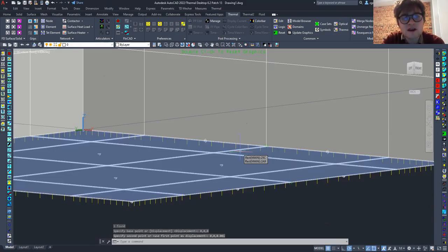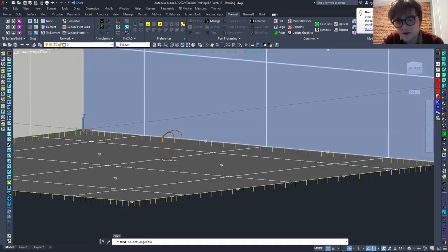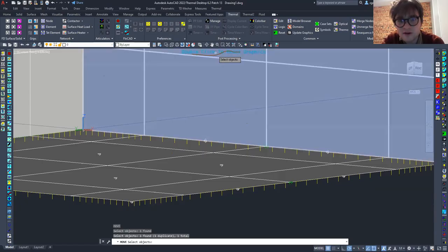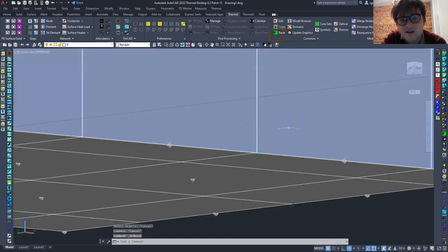And to reset graphics, you can double click that thing at the top, because see, it still has these wonky little lines. It's because it doesn't re-render these live, so you need to reset the graphics every time. Either you can double click right here, or there's a green button somewhere up here in the ribbon. I can't see it because my Zoom thing is in the way. Oh, right here, this reset button. Either of those will reset your graphics so you don't see those annoying yellow lines anymore.